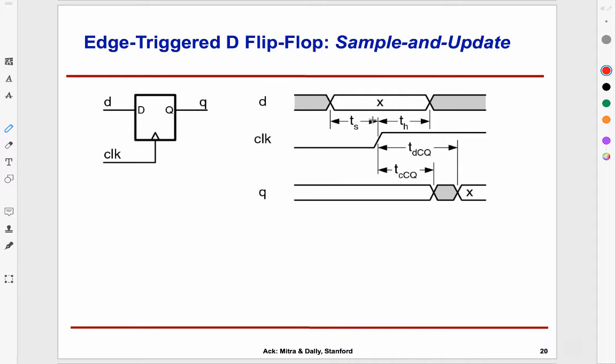Now, if I were to look at the timing characteristics, combinational logic we understand, but let's look at the flip-flop. What are its timing characteristics? So thus far we have had a very idealized picture of a flip-flop, right? It has a clock, an edge comes, it grabs the input, puts it on the output, and also remembers it. But if you analyze it at a circuit level, obviously there are going to be delays, and the question is how do we characterize it?